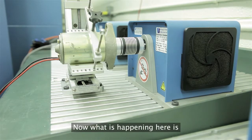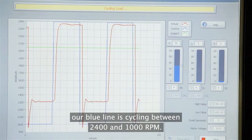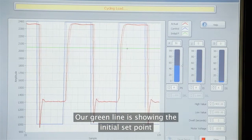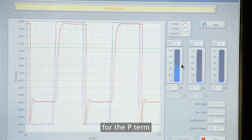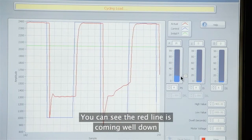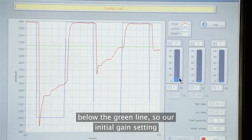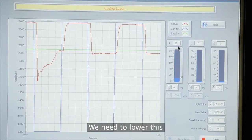Now, what is happening here is our blue line is cycling between 2400 and 1000 RPM. Our green line is showing the initial set point for the P term, and the red line is showing our system response. Now you can see that the red line is coming well down below the green line, so our initial gain setting is too great, so we need to lower this